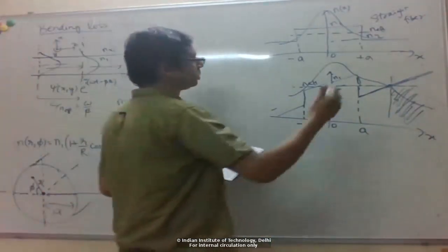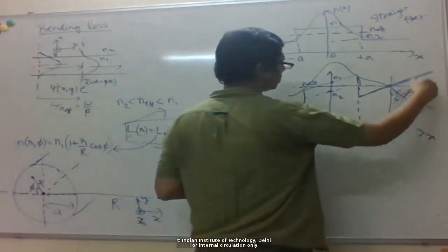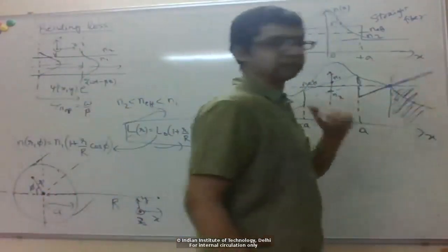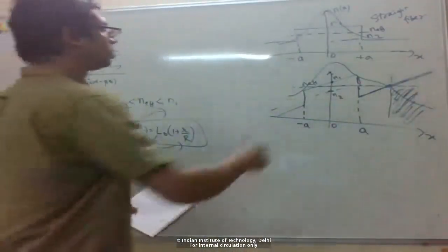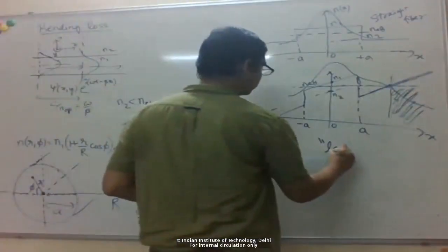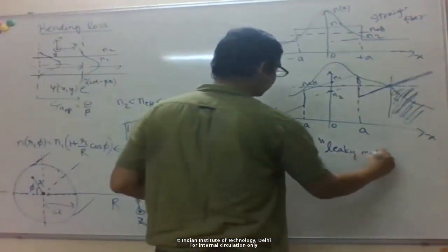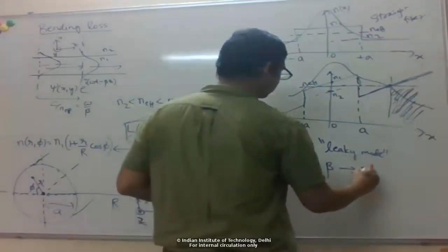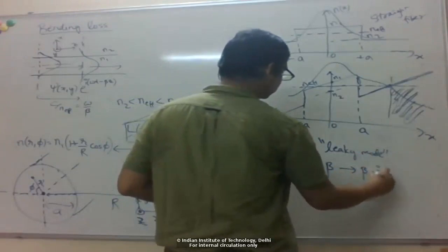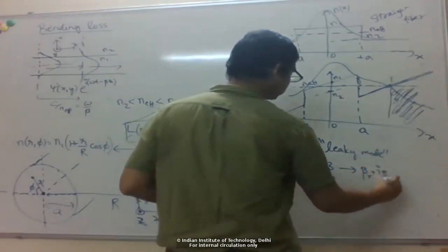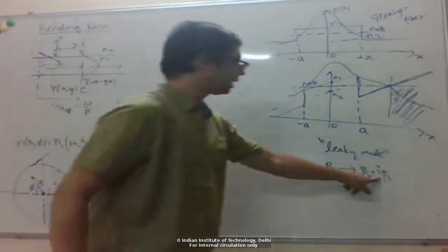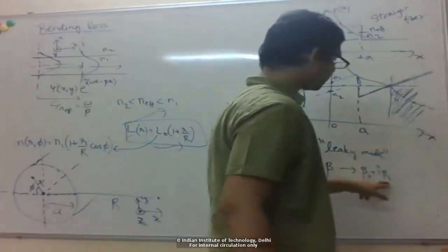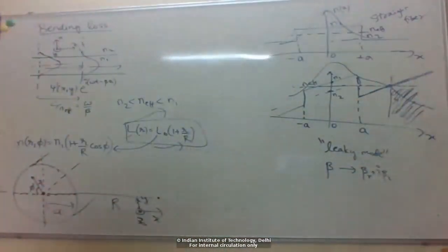Okay, so you can see that this part of the power has to be radiated away, right? So a fraction of the power will keep being lost as the mode propagates. So this is not a proper mode. It's what is known as a leaky mode, which means that now your propagation constant, instead of being a real number, has an imaginary component, which gives basically a loss. So this part of the power being radiated away is giving me an imaginary part of the